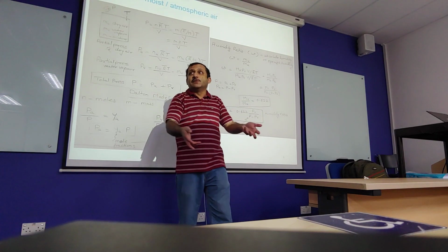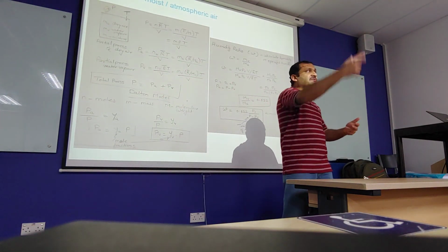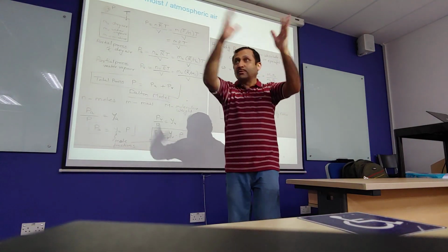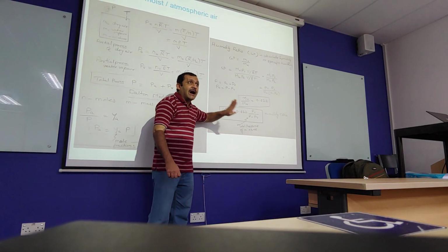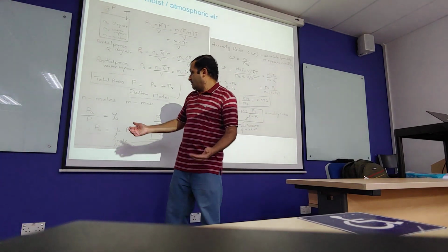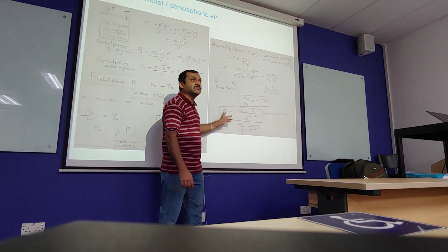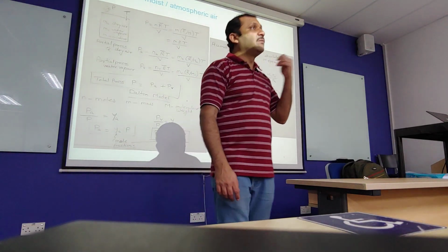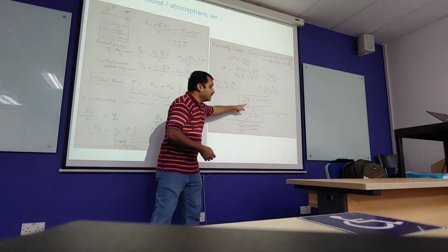Because the barometer doesn't know how many water molecules there are, how many oxygen molecules, or nitrogen molecules. It's just total pressure. Whatever pressure the sensor is sensing, it just gives you a number for the total. Now, how would you convert that number into partial pressure, either PV or humidity ratio, omega? How can you estimate one of those? Why do you need to estimate these numbers?